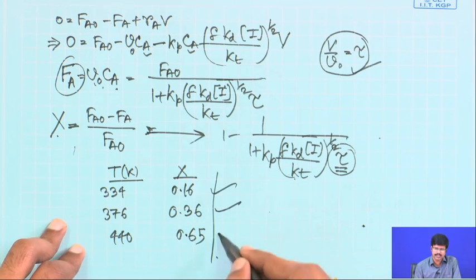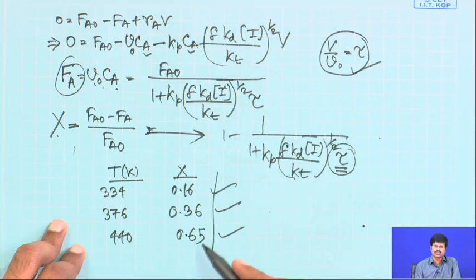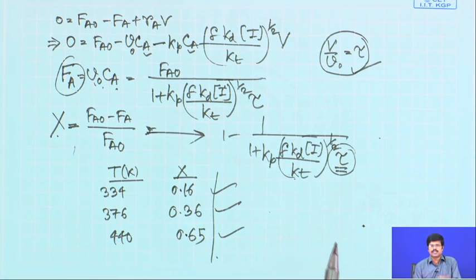So, you have these 3 steady state operating conditions that you can choose from at that particular inlet temperature and at all those fixed temperatures that we have. So, inlet temperature is fixed, your heat transfer fluid temperature is fixed, your UA, which is your heat transfer coefficient multiplied by the area of heat transfer, those things are fixed, and then you can have this solution.